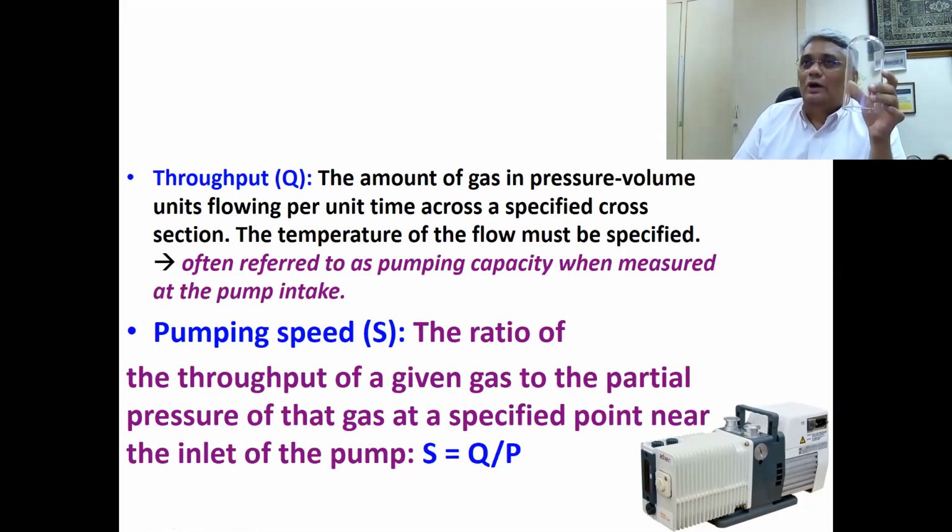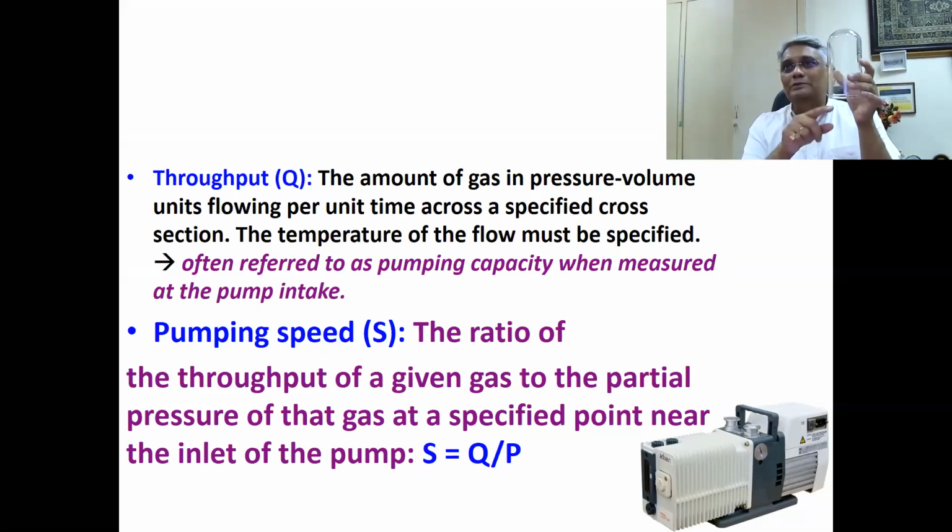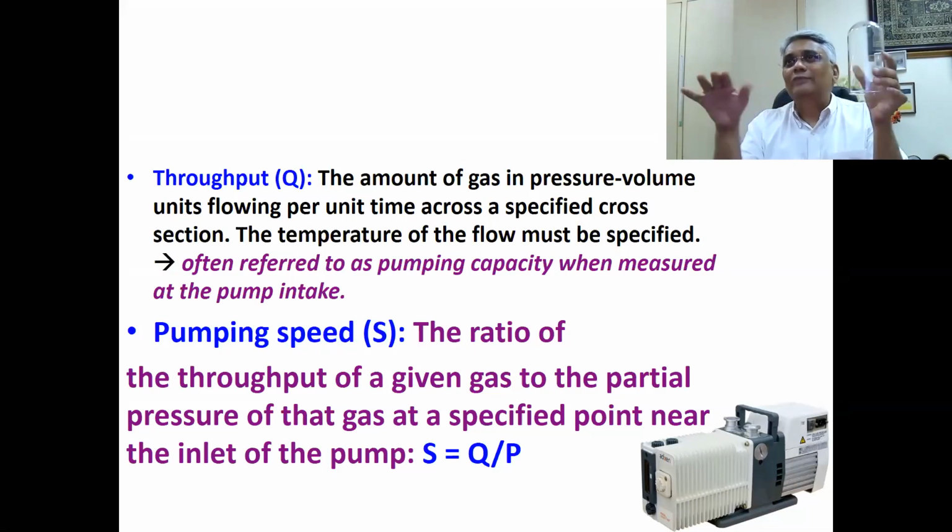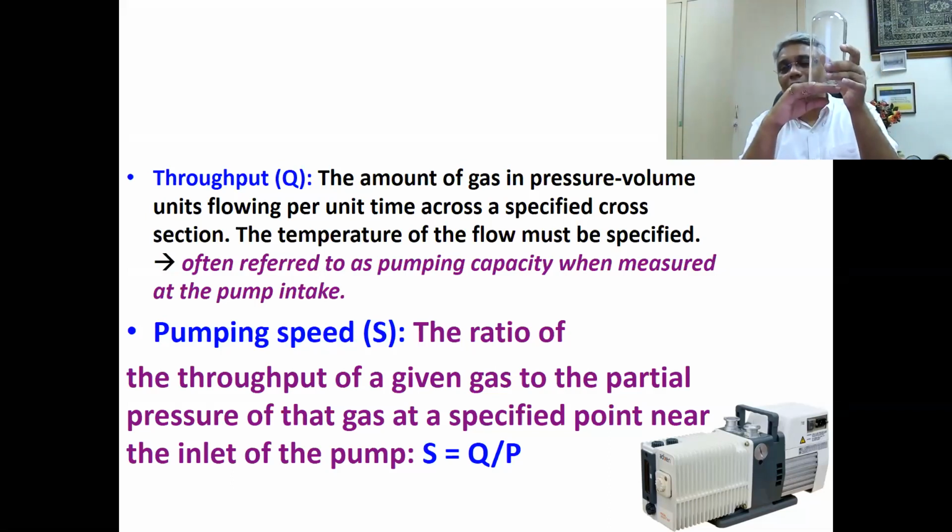Okay. So at the most, you can reach the pumping value of the pump here, and normal calculations show that the pumping speed at this point is half the level of the inlet pumping speed. That's all. Of course, the ideal situation is, imagine the inlet is directly connected to this one.